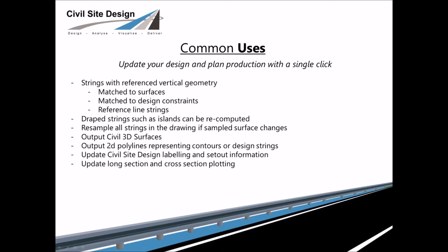You might use threads to update drape strings in your model, and the order of operation might be really important. So you might only want to update the drape string once other actions are performed. So threads allow you to easily order how these actions happen.